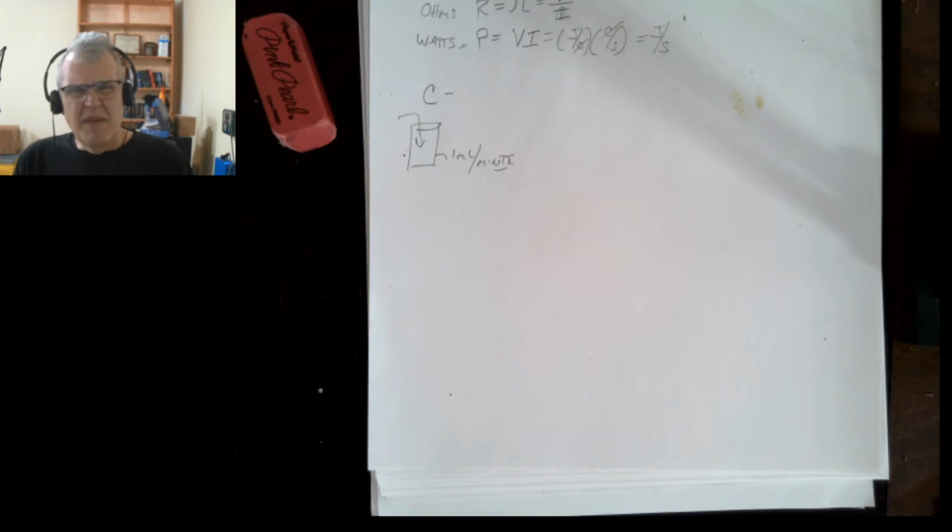If I've got an 18650 battery pack in a 7 series configuration, that is 7 batteries put in series, typically we would consider that to be around 24 volts, even though if you figure it out, it's much higher than that. You take from the top end to the bottom end and use the nominal voltage. I think even the nominal voltage of that is higher than 24. We'd have to calculate it out. But you don't usually go through the trouble of integrating the area underneath that curve because as you're discharging the battery, state of charge is going to have an effect upon the voltage that the battery has, and so it can change things.